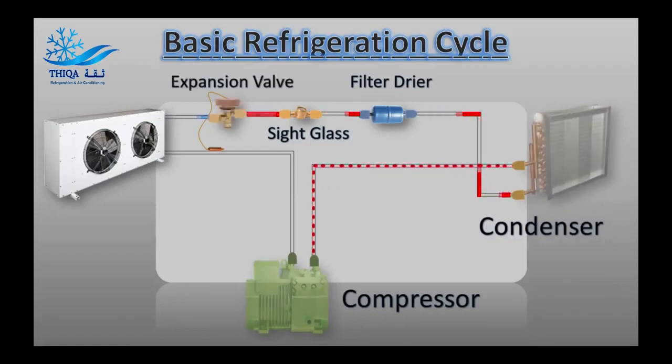Third, the expansion device. The expansion device creates a drop in pressure after the refrigerant leaves the condenser. This pressure drop will cause some of that refrigerant to quickly boil, creating a two-phase mixture. This rapid phase change is called flashing, and it helps tee up the next piece of equipment in the circuit, the evaporator, to perform its intended function.